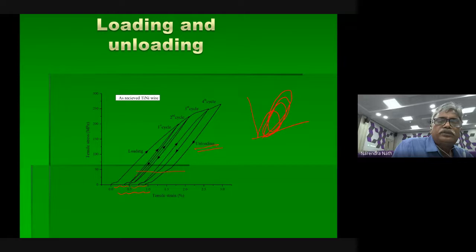But if you use high-end Instron or any high-end tensile machines with dynamic characteristics, it comes like this. Going, so this is the plateau. It is coming back here, so that means exactly to the origin, so no residual stress. If it comes with time like this, then this is the residual stress accumulated. So you need high-end, in the sense sophisticated, measuring devices.